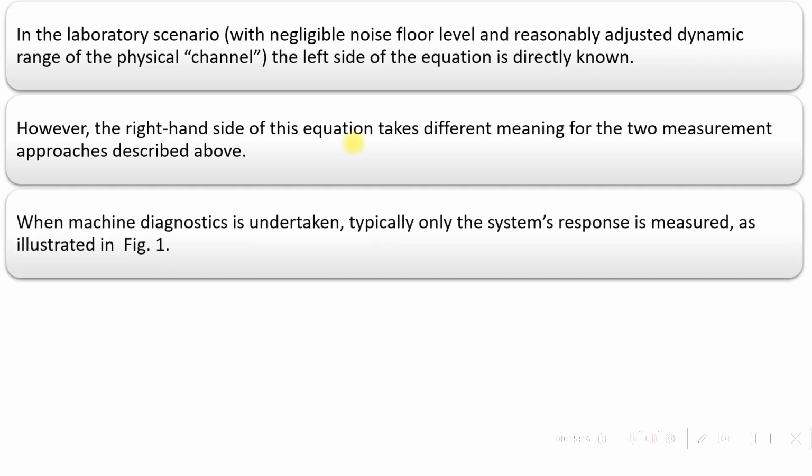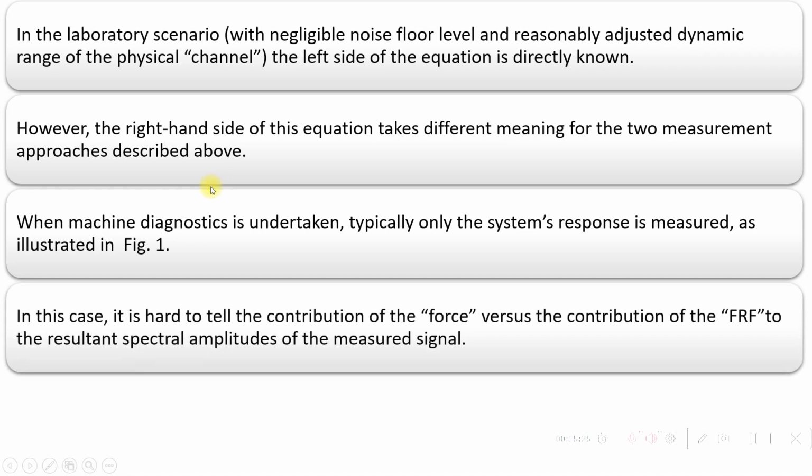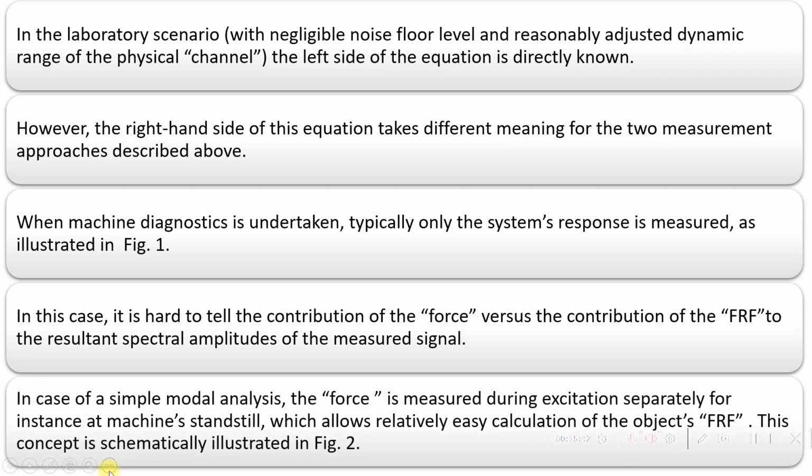When machine diagnosis is undertaken, typically only the system's response is measured, as illustrated in figure 1. In this case it is hard to tell the contribution of the force versus the contribution of the frequency response function to the resultant spectral amplitudes of the measured signal.